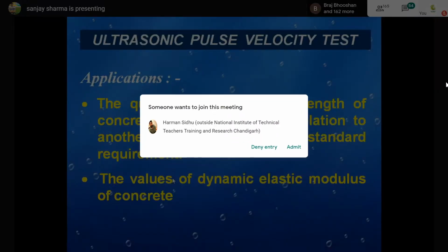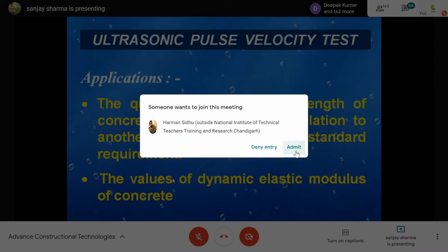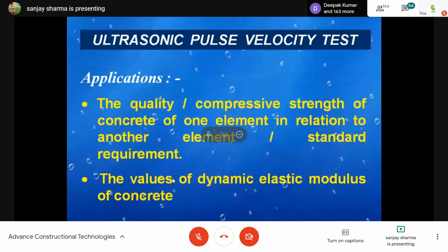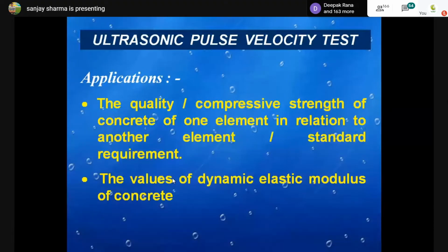So basically the ducts, the wires which were there for tensioning also got stuck in that, and that tensioning became a bit of a problem afterwards. So those people, I don't remember exactly, because I was not associated afterward, but then they searched for some sort of chemical to dissolve that epoxy in that material, and then it provided the required type of prevention, and then it worked very properly afterwards.